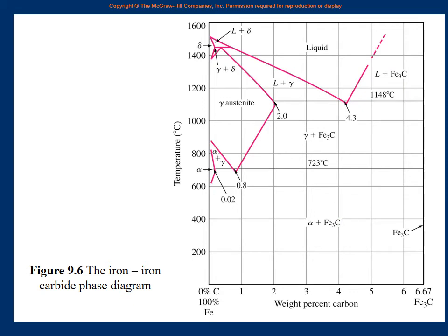So we are just trying to explain to you, and you should not worry. What you will see is that normally steel has only a small amount of carbon. This is 0.02%. There is alpha here. You see this inside here is alpha. This whole thing is gamma. So in between here is alpha plus gamma, right? This is alpha. On your extreme left, this small portion is alpha, and it finishes at only 0.02% carbon.